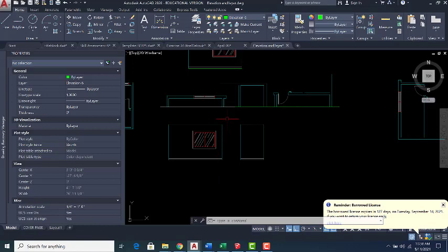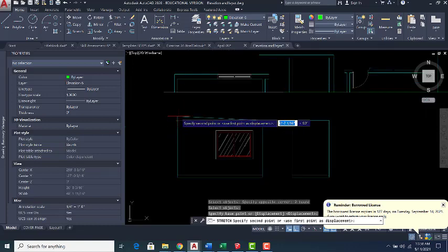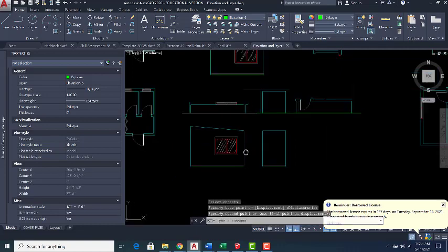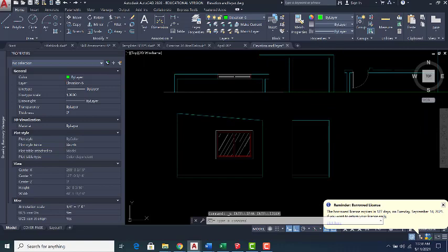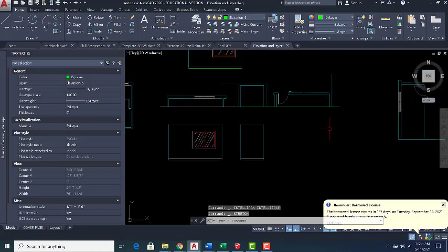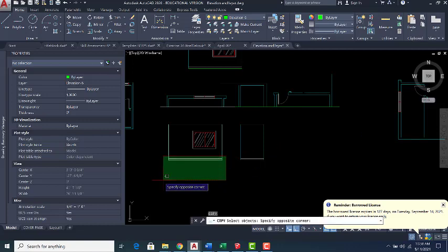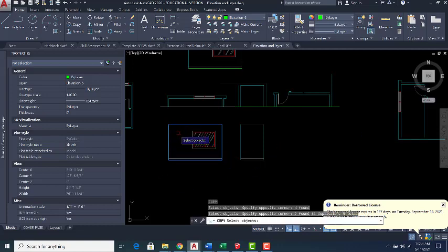The reason that I mirror sometimes is that there are times when there is a slope in the ceiling. So mirror is the safest thing, because when you mirror, for sure you're going to get it right. In this case, because everything is level, the ceiling and the floor, you can even copy. So again, I'm showing us a different way, but you have to think about every situation might be different. In this case, I don't need to mirror it.